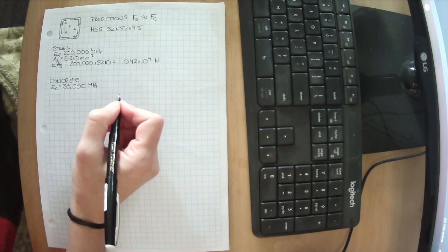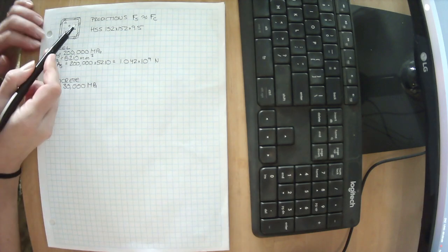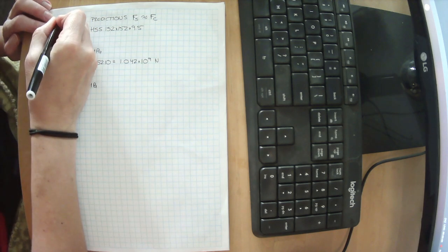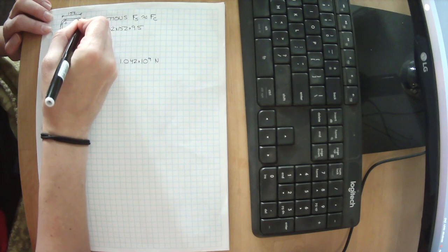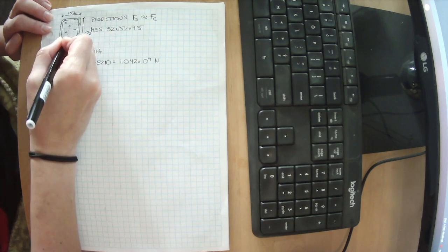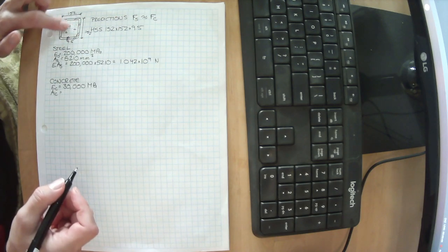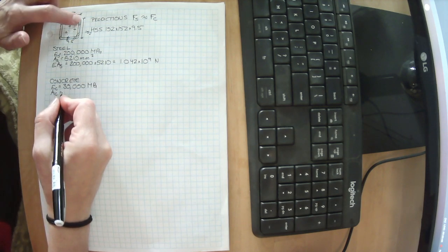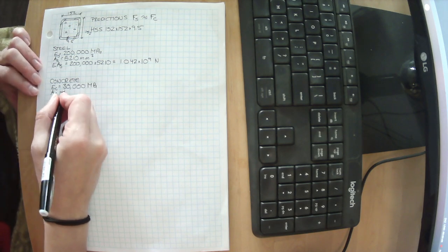Well, let's figure out what the area of the concrete is. So the area of the concrete is this bit in here. We know that this is 152, and this is 152, and that dimension is 9.5. So let's figure out what amount of concrete we have there. I'm not going to worry about the rounded edge too much. That's maybe refining it a little too much.